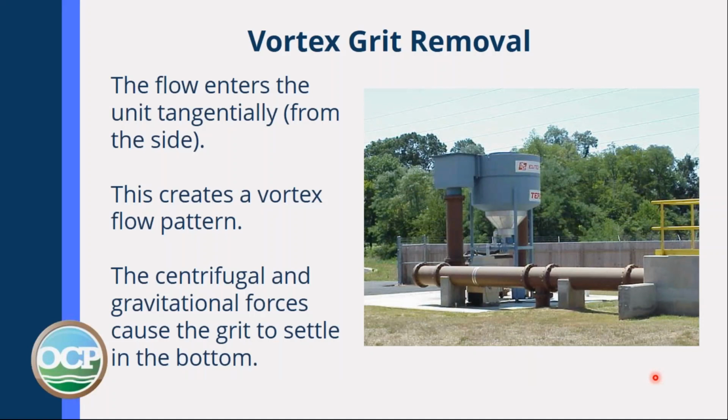You can use something that looks like this. This is a vortex. This is very similar to the aerated grit chamber, but it's upright rather than lying flat. And again, as water comes through here, anything solid will sort of settle in the bottom of the tank here, and all other suspended material will leave and go into the wastewater plant.